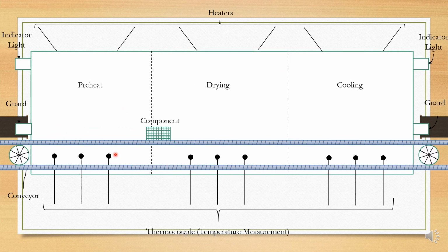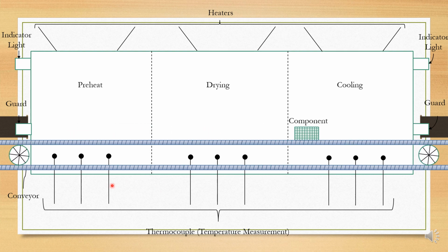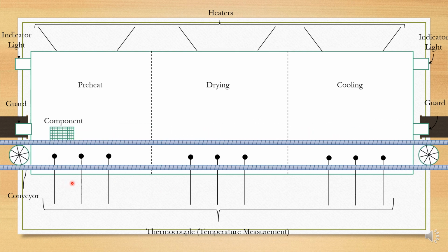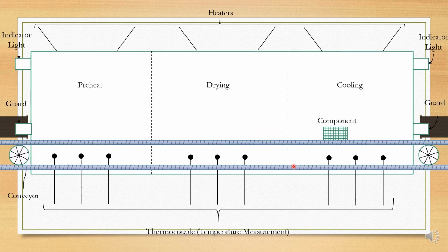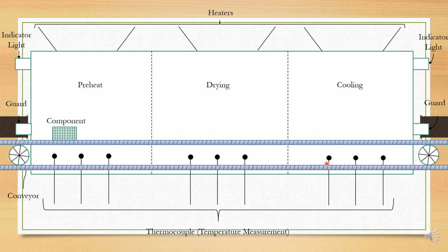The second signal is conveyor startup. This signal is initiated if all the heater areas are switched on. For example, suppose the conveyor fails to reach the desired speed within 30 seconds. If the speed fails to be reached within 30 seconds, the conveyor fault signal is activated and it immediately stops the conveyor.